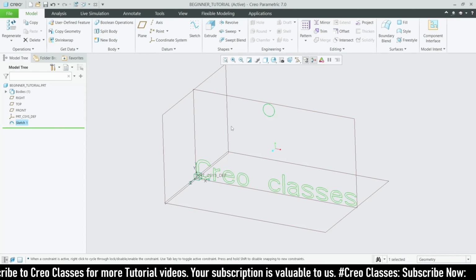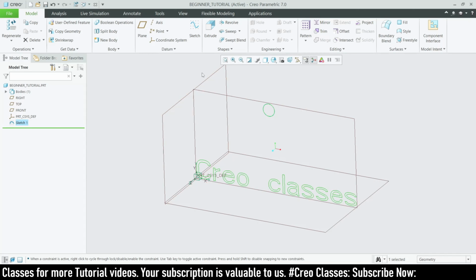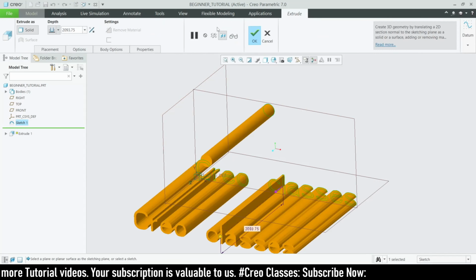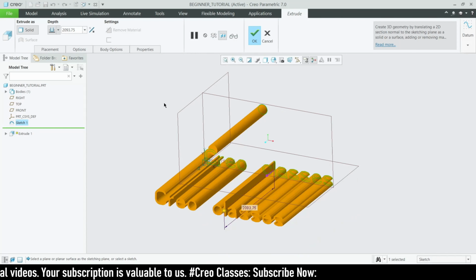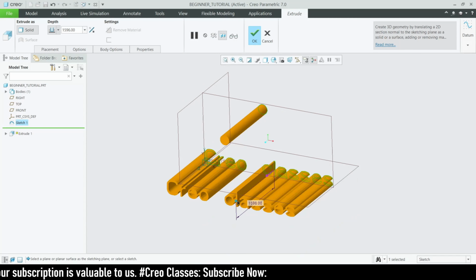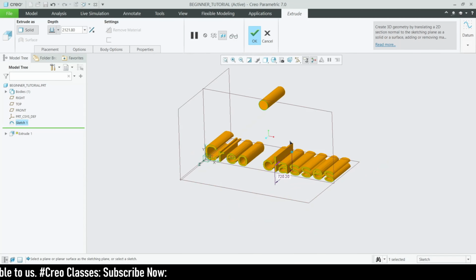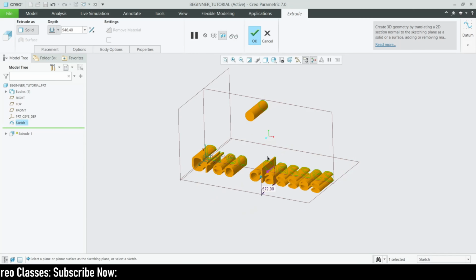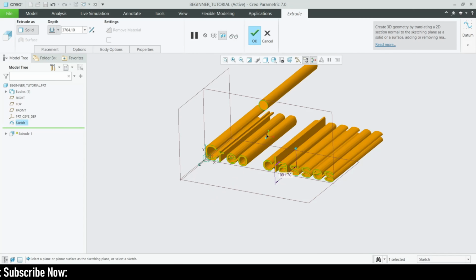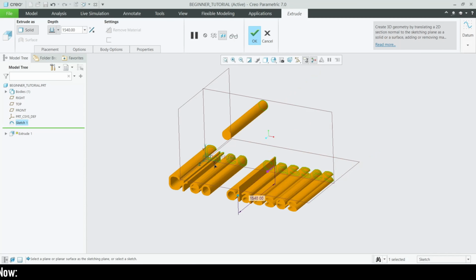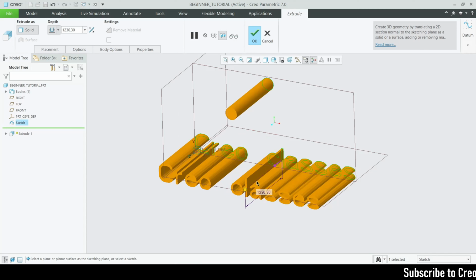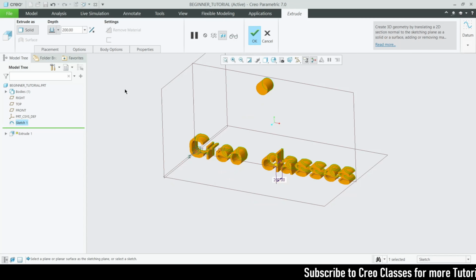If you need to convert this into 3D, you can directly go for extrude. After getting extrude, your part will be viewed like this. As you can see the yellow color dot here, you can drag our extruded part to set how long we need the extruded 3D length. Instead of dragging like this, there are two ways to add values for length. Here you can add a value as a length, or else here you can also add a value as a length.